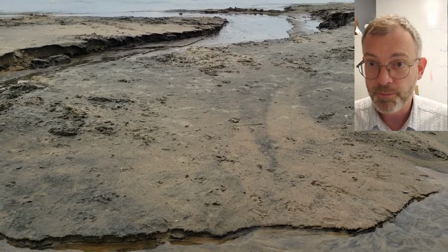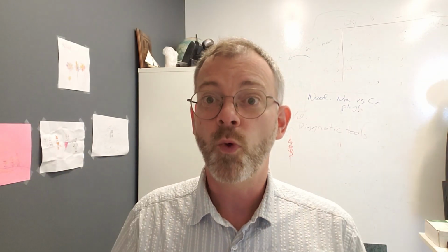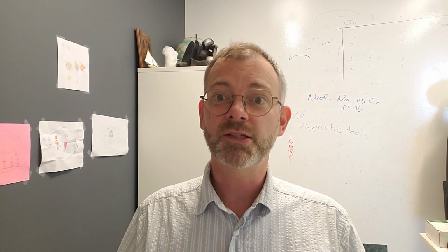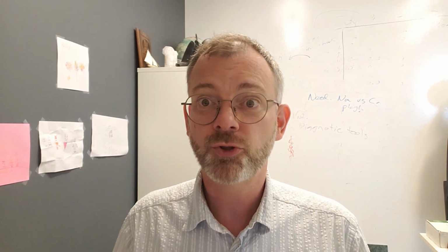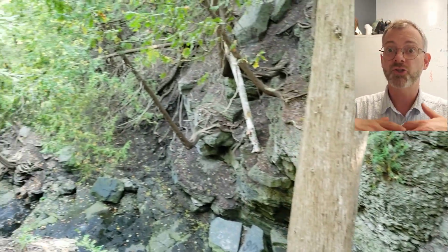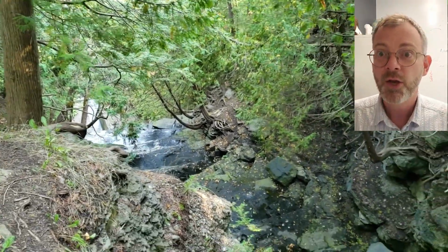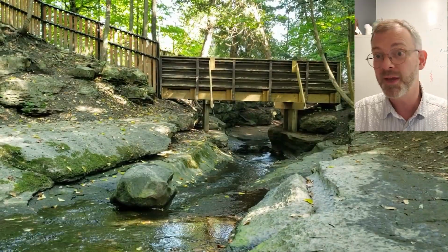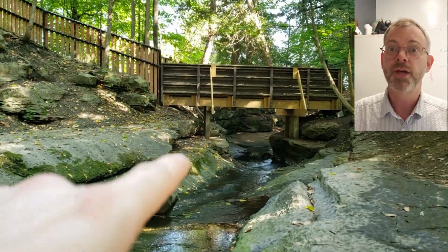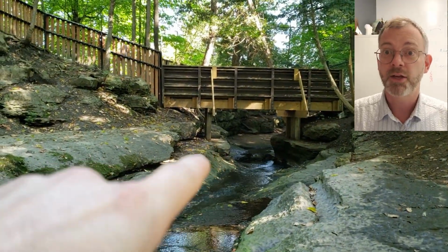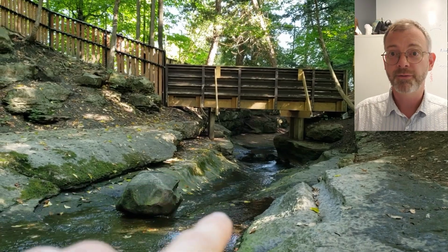And we can use that to make our geological model and help us to predict where spatially those layers may exist. And that can be useful for trying to find aggregate, but also for engineering purposes, trying to construct something that may want to cross such a river channel. We can understand where the weak layers may exist and how deep we may need to anchor things or drill in our piers to make our bridge foundation strong enough and durable enough.